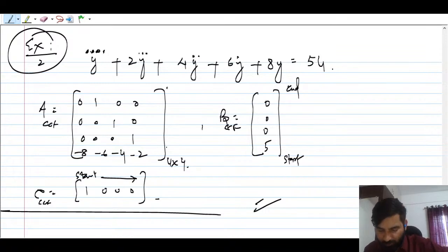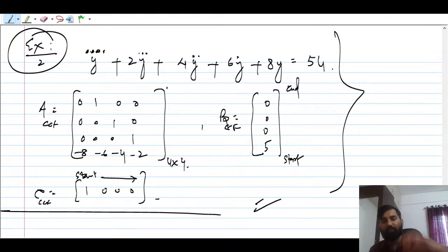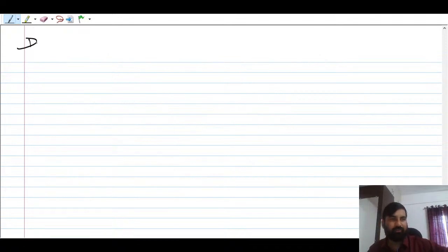Now if you want to find OCF, how do we find that? Just take the transpose of the A matrix, that's it, and you will get OCF. So please remember that this is the first question that you can get: state model, or you can say finding the state transition matrix from the differential equation of any order. So you can get it like this. And there is a detailed procedure as well. So let me tell you one detailed procedure as well.